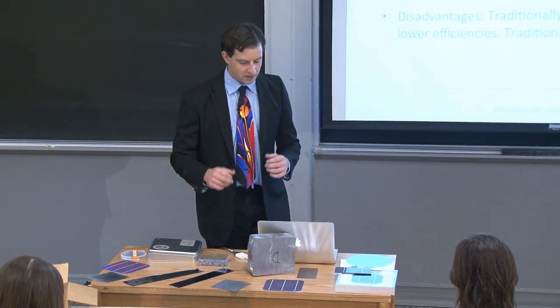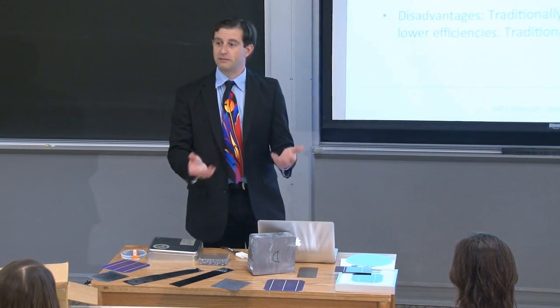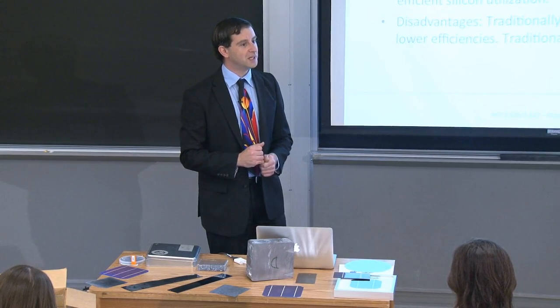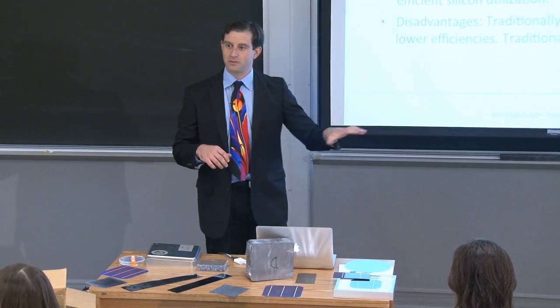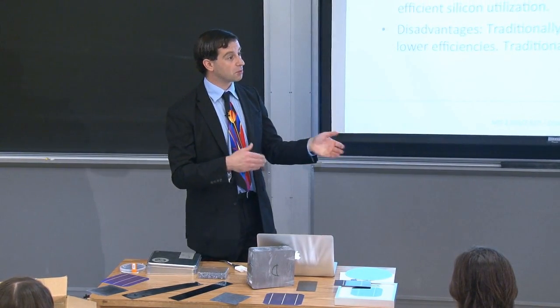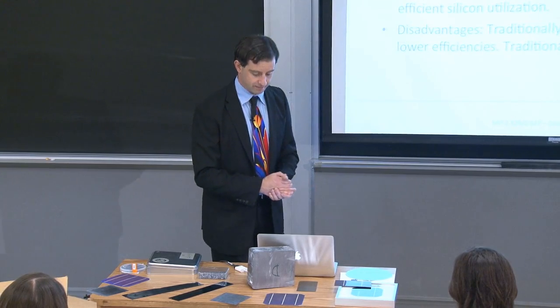Why is that? Well, if you want to make a cell out of it or a solar cell device, you'd want to make sure that you can take advantage of the same manufacturing equipment. And that's just a plug-and-play drop-in replacement. If you require customization of the downstream components on the cell and the module level, you'll wind up having to invest more money in those processes, which might counteract the advantage that you get out of using less silicon.